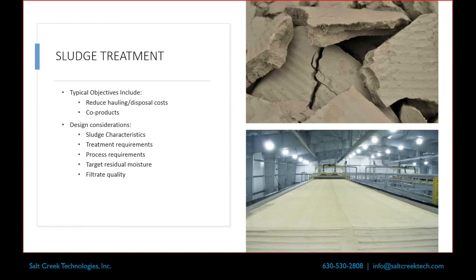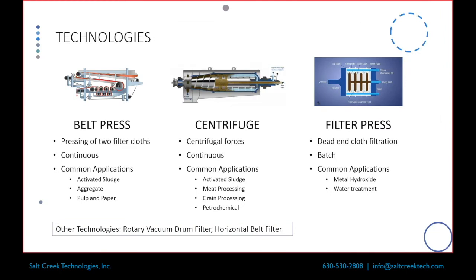Things you want to think about, though, on top of that are target residual moisture, filtrate quality. Are you looking to put the filtrate back at the front of the plant? Or are you looking at keeping it in or discharging it directly? All those things kind of need to be thought about with those.